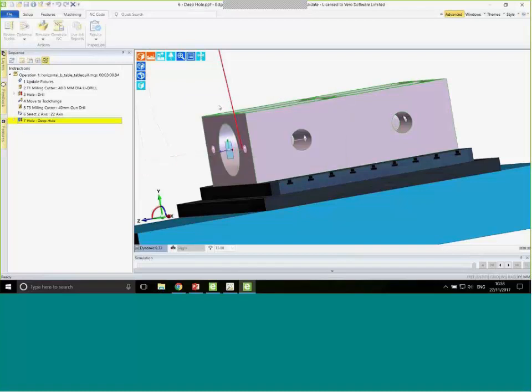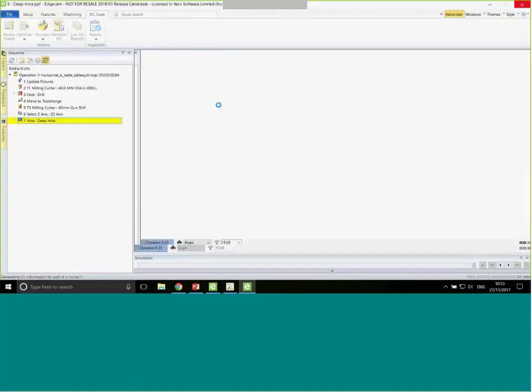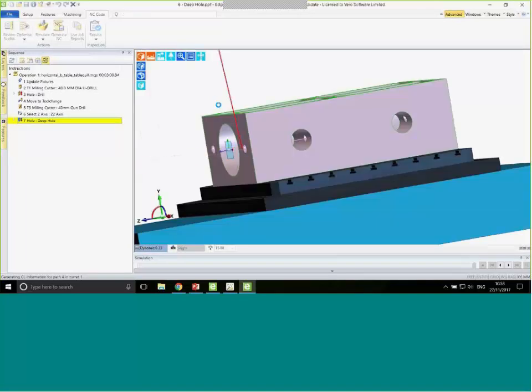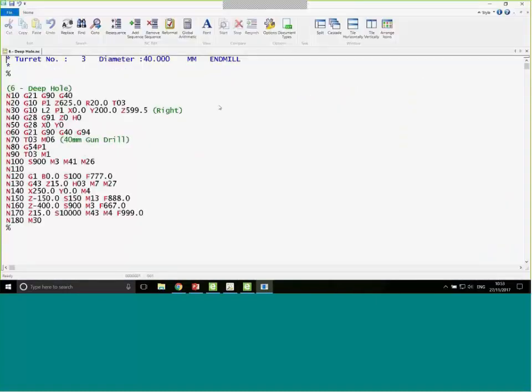But what's more important is that it switches the spindle condition depending on where it is, on the stage of the drill. So it's on the approach. It may not turn on the spindle, but it might simply slow feed into a pilot hole. As it makes its way back out of the hole, what we'll probably see is it will begin to switch off the spindle, or sometimes people like to reverse the spindle, and withdraw it at a different feed rate.